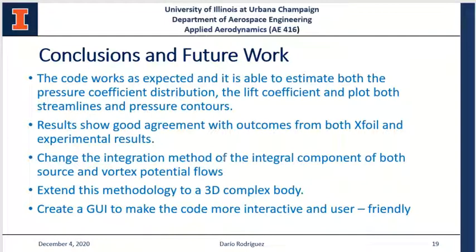And also probably I need to check how increasing the number of panels affects both the leading edge and the trailing edge, because those sections are sensitive to the change in the number of panels. Probably a cosine distribution would not be necessary once we reach a certain number of panels.